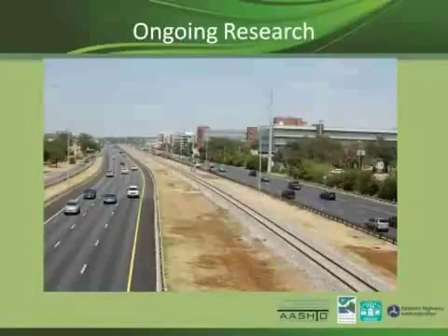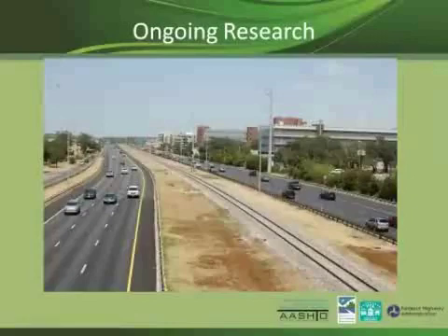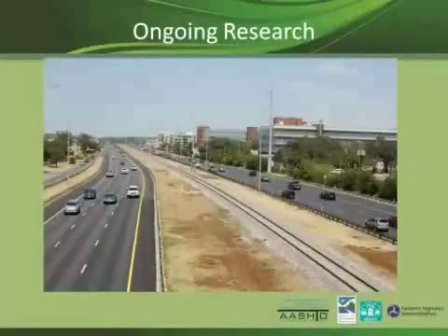So we're doing some monitoring here now. I have my student Laura in the office with me, and she's monitoring 2 sites on a freeway here in Austin, Mopac. The interesting thing is, first, it's wider, so it's 4 lanes instead of 2 or 3. It has curb and gutter instead of a rural cross section. And so we're still seeing really good water quality, still exceeding 92% suspended solids removal.